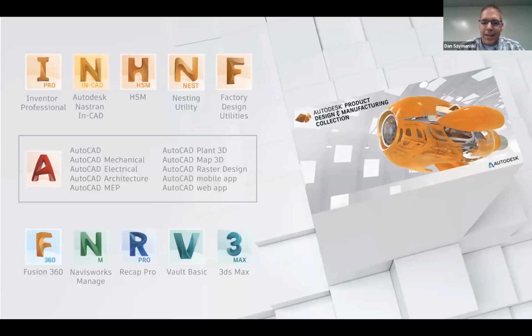So again, it is just taking topology. The bend allowances and the sheet metal styles are still all in place for standard sheet metal parts. We should still use that for regular typical use cases for sheet metal. But again, it's just another tool that allows you to work around a scenario where you might not be able to extract a legitimate flat pattern. Thanks, Dan.